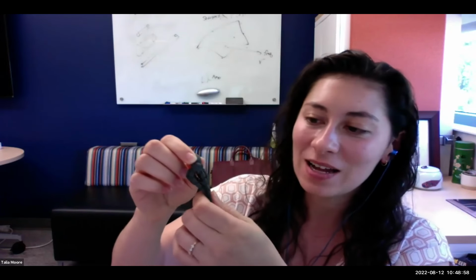Now, the other really terrible thing about SLS printing is that it's kind of like excavating in terms of post-processing. You're sort of like an archaeologist and you have to dig out every single piece and brush it with a toothbrush. I actually recommend dental tools if you're going to get this. It's a giant pain. And that's because this powder is a lung irritant and it's really bad for your health. So if you're going to get an SLS printer, you definitely need to get proper ventilation, a lot of proper gear. It's also combustible and an explosion hazard. So you've got to make sure you have all of the safety precautions available.